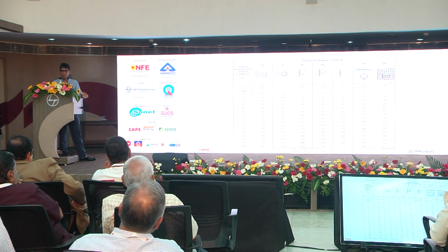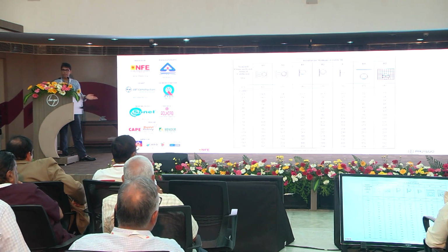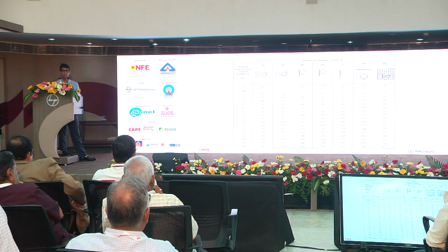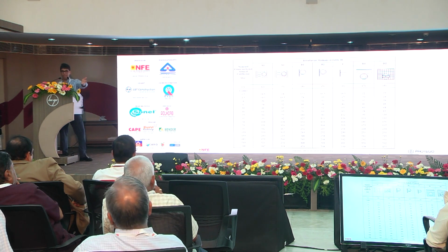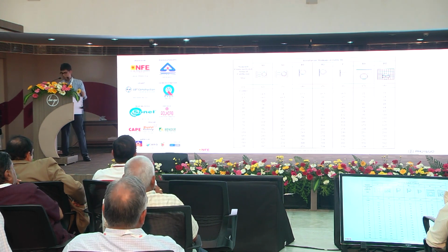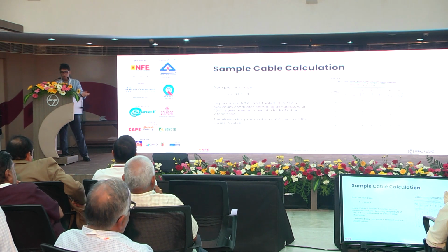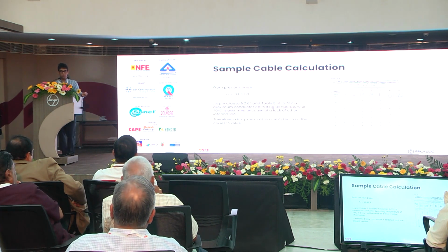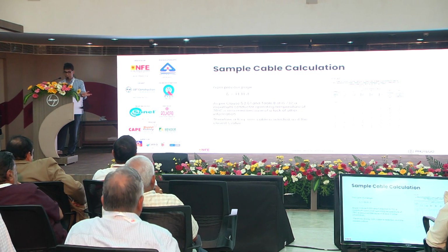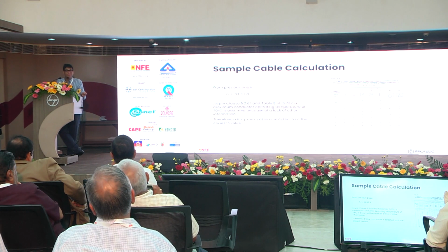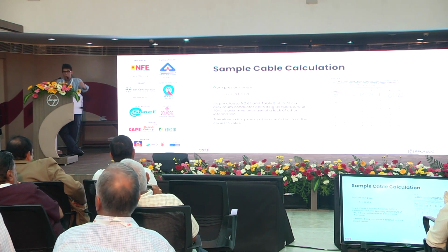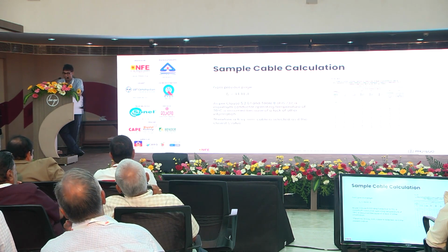Now this is an easy one. The method is D1. Please, you know the current carrying capacity. What size of cable can be used? Minimum. That's right, 6 square millimeters. 10, somebody said 10 is also fine. It gives you a greater, but 6 is correct. So we know 70 degrees is the maximum assumed because we lack other information, therefore a 6 millimeter cable is to be selected. Congratulations, you have done one of the most fundamental things in electrical safety design. I hope you take this forward when you do your actual projects.